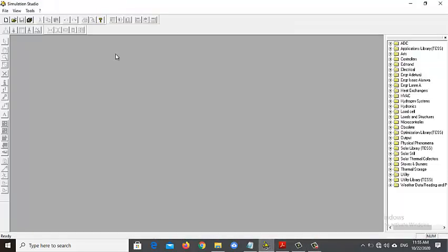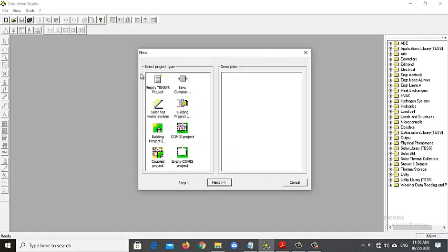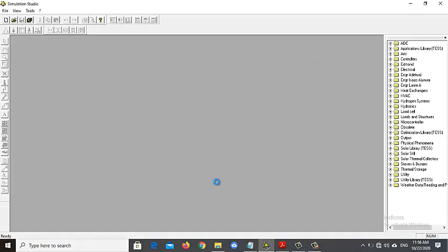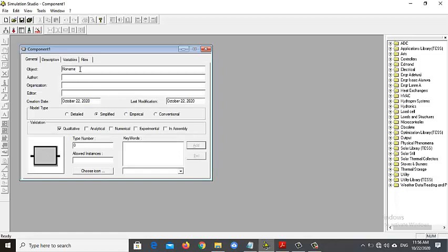Alright, let's go straight to Trnsys. Go to new component, create. You can call it whatever you like. Sample convection. I want to name this, let's say I use a number like 500 for example, and allow my instance 1. I need to choose an icon, and because I don't have a readily available image, I'm going to call up Paint